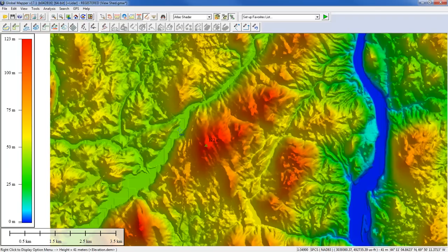We're going to use the same parameters that we had for our line of sight, a 10 meter artificially exaggerated height, looking at a 2 meter person, I guess. At some point, what coverage do we have? What areas would we not see that person within the extent of our analysis area? For this analysis, I'm going to simply use the digitizer to select that source point. I'm going to click the button in the toolbar to generate a viewshed.